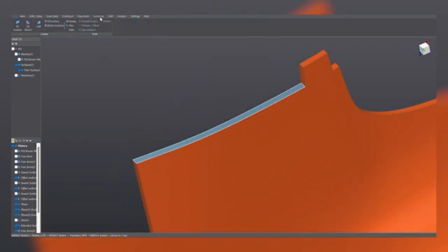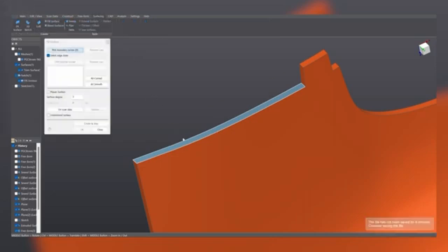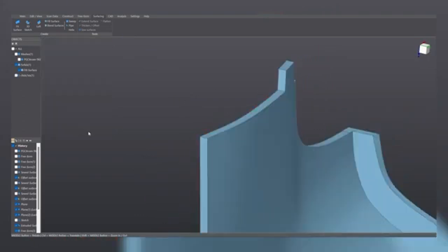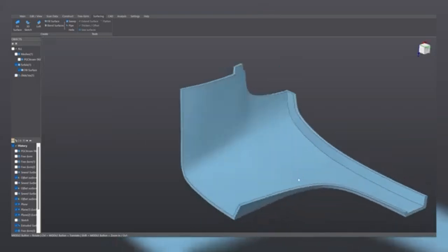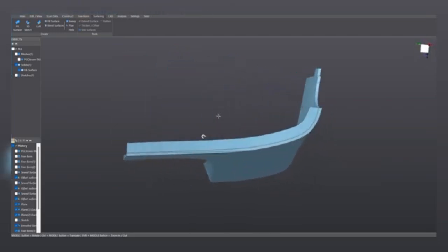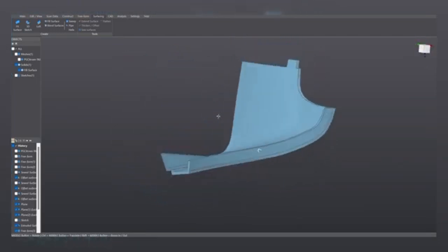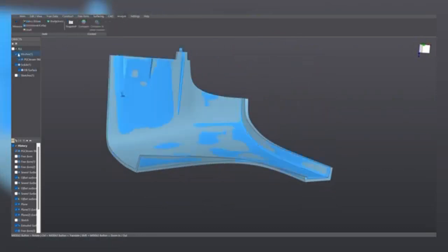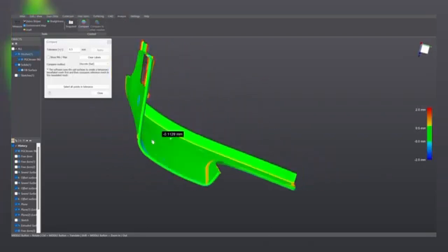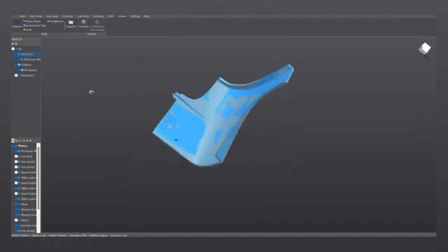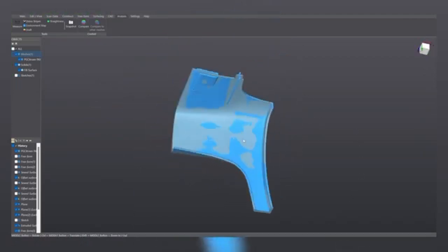And to solve it, we go to Surfacing, Fill Surface. We pick one of the boundaries, and the software automatically detects all the contacts of this surface. As soon as I click on OK and the surface is attached, the software recognizes that all these surfaces intersect with each other, enclosing an empty volume, and therefore it becomes, as you can see here, a solid. Let's take a look at the comparison with the mesh. We can observe the result so far, and this would be the end of the surfacing task.